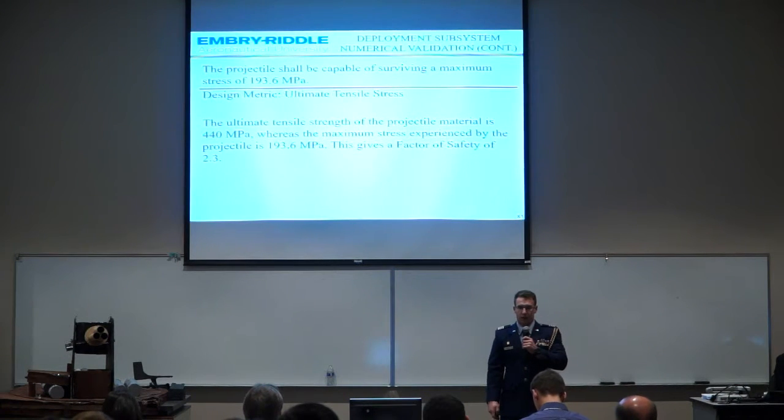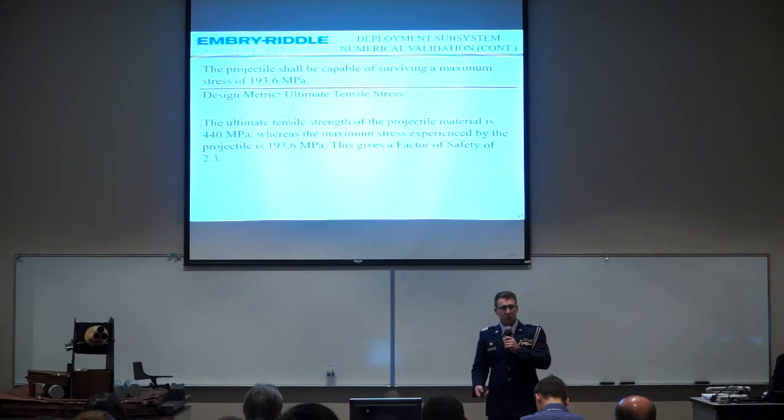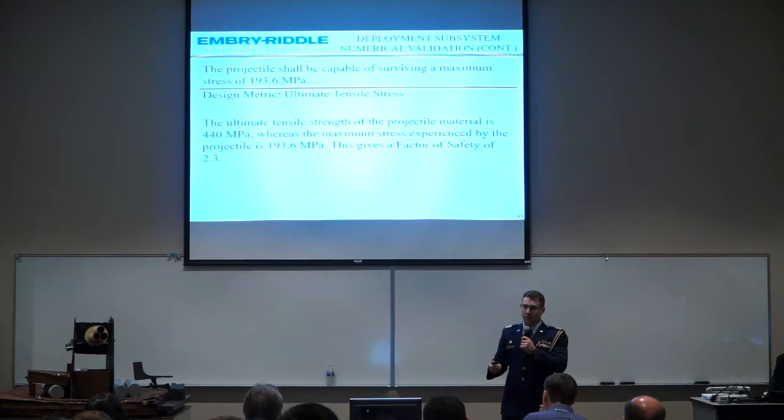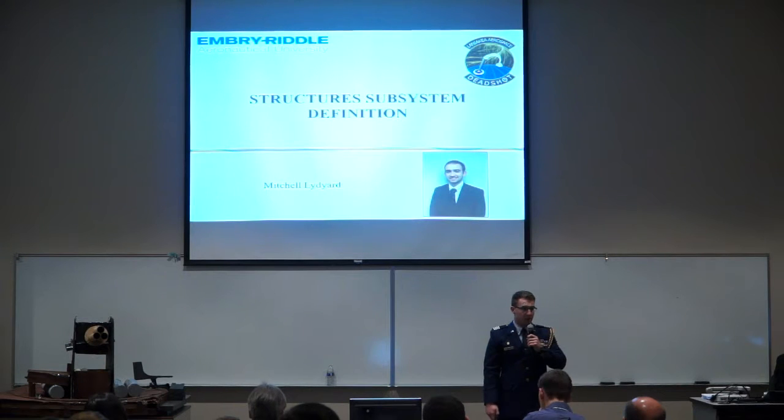And finally, the projectile shall be capable of surviving a maximum stress of 193.6 megapascals. Our design metric for this was ultimate tensile stress, and the ultimate tensile strength of that low carbon steel that we will be using is 440 megapascals, which gives us a factor of safety of a little over 2, which does validate this requirement. At this time, I'd like to hand over to Mitchell Lydiard to discuss the structure subsystem.